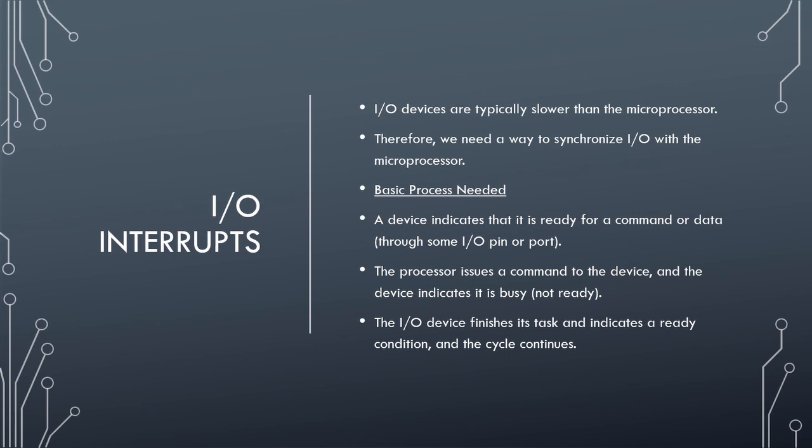That's why we don't really need to worry about it for simple projects, but for more complex things, sometimes we need to use interrupts as a way to sync things up so that, for example, our microcontroller isn't sending data faster than our output can receive it and respond. Think of the LCD display as one of our digital outputs. If the microcontroller is telling the display to display words faster than the display can respond, we're going to have an issue.